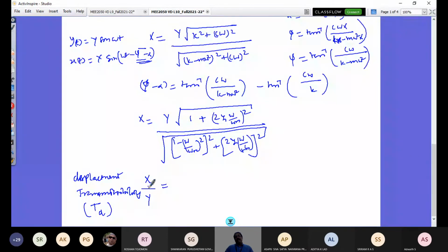It's a dynamic amplitude response of my mass, my vehicle body in vertical direction, to that of the amplitude of road profile or the base excitation. So base is moving like that. So I can have this fixed road wavy and then ride my vehicle. There I give my displacement of my road and then excite my vehicle in real time test. Or you can also have that vehicle seated in a laboratory on a 4-post hydraulic jack, and all the posts would go up and down with a sinusoidal wave,